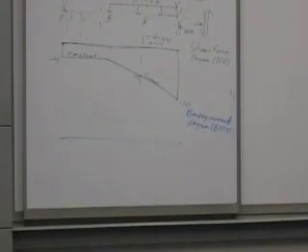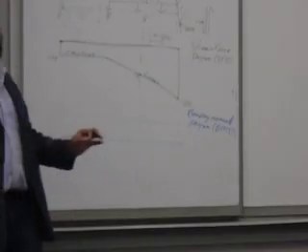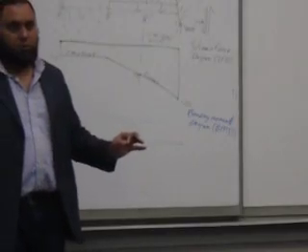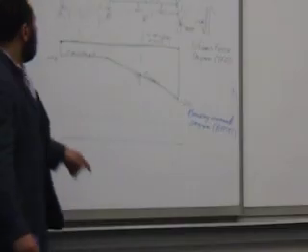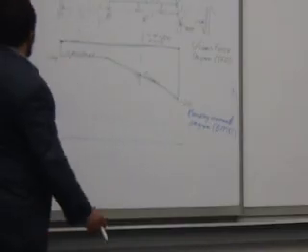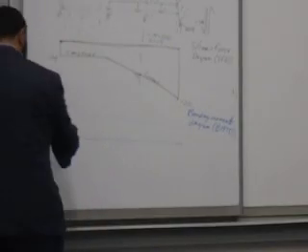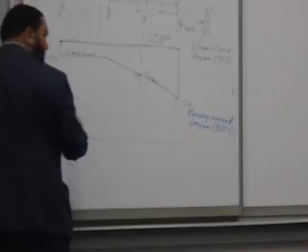Good. So the bending moment is even a little bit easier to do. Why is that? Because a moment is actually something at a point. You take a moment at a point. But if I'm standing at A and I'm taking a moment, I'm looking there, will I see anything? Air, right? So the moment is zero here. That's it.